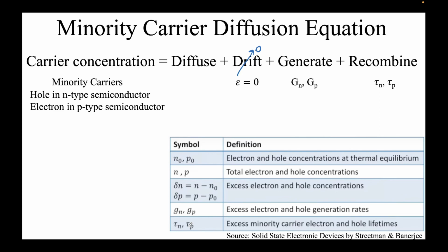You know that information. But the important question is, why are we even ignoring the majority charge carriers? I mean, it's not like they're not present. In fact, they are in majority. So why are we so adamant on ignoring them? What is happening in the system that makes us ignore them, right? The answer is low level injection. This means that I am injecting not a very high amount of charge carriers.